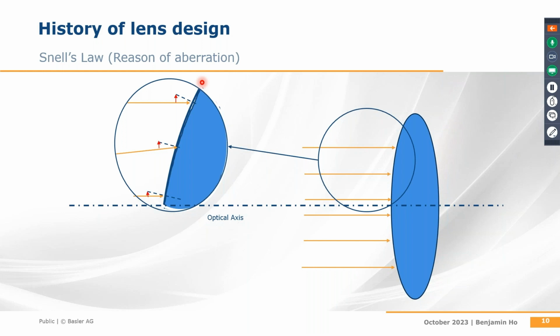To reduce the lens aberration, we should use the light beam only near the optical axis. How can we do that? The easiest way is to reduce the lens aperture size. By reducing the lens aperture, all the light beams at the edge sides are blocked by the iris, and only the light beam in the center can enter the lens. So the smaller we close the lens aperture, the less aberration we have, but the diffraction effect is increasing. What is diffraction? In the next topic, we'll tell you more.